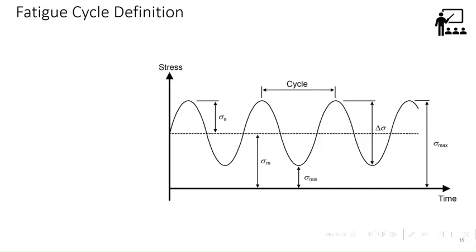constant RPM of engine and all. Those are constant amplitude loads, or your flap deflection, retraction. There will be one duty cycle that will consider a constant amplitude loading. But in general, to understand variable amplitude loading, you have to start with the constant amplitude loading.